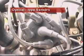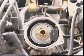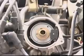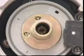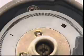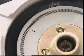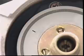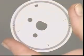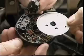Crank angle position and engine RPM can be detected optically. A signal rotor plate is attached to the distributor shaft. It has 360 slits at 1 degree intervals on its outer edge. Inboard of the 1 degree slits are 4 slits, 1 for each cylinder. They provide the reference points for the ignition timing and the fuel injection. One is larger than the others to provide the signature effect for the number 1 cylinder.